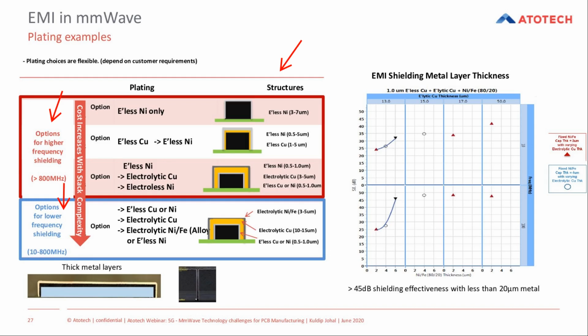Another approach was the higher frequency applications where skin depth is reduced, effectively decreasing the conductor cross-sectional area, and the conductance decreases and current absorption is reduced. Therefore, higher conductivity metals such as copper are needed to counteract the skin effect and sustain the shielding through absorption capability, reducing the current, and in turn lowering the generated magnetic flux.